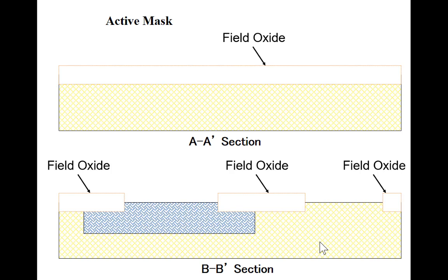I should point out what this field oxide is doing. We're going to eventually run metal around to interconnect things together. Anytime you run a conductor on top of a doped region, you try to pull impurities to the surface. You try to create an inversion layer. If you have your metals close to the silicon, then when you put a voltage on the conductor, it will create an inversion layer and short everything out. So what we do is we put the insulator on, so our conductors are way above the surface, so that the capacitance between the gate and the silicon is so low that we don't get enough force to create the inversion layer. So the field oxide then provides isolation between devices. It provides isolation by essentially raising the threshold voltage up to a very high level. Make sense?